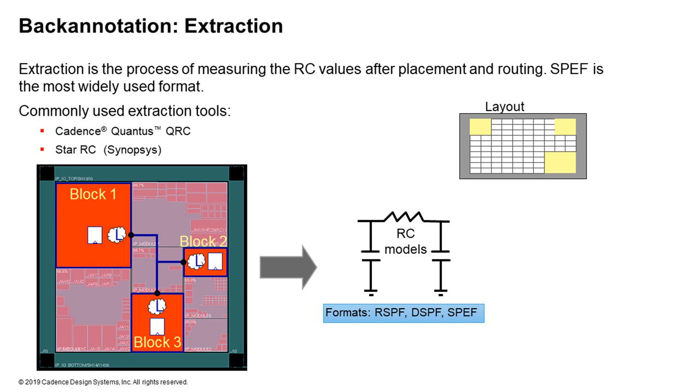And you can take either the SDF to feed back into your synthesis, or the SPEF itself can be used to feed back. So either way, this process is called extraction.